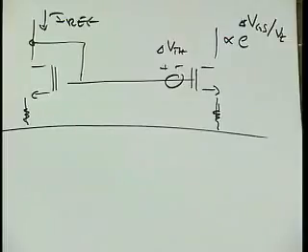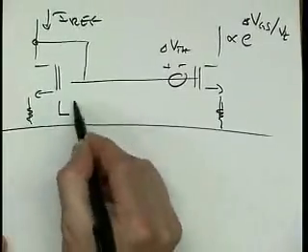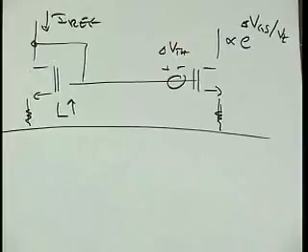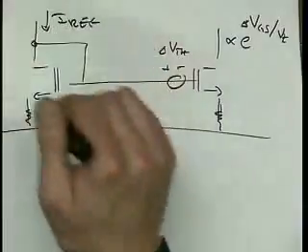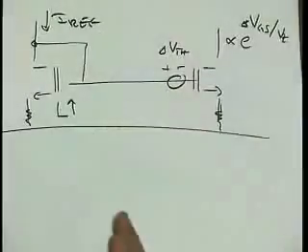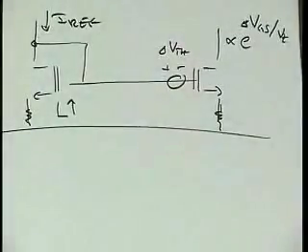What would you do rather? Yeah, specifically, what do you make bigger? Yeah, you make L bigger. That brings the device out of weak inversion and increases VGS, and we don't have the problem anymore. We are not nearly as sensitive. It reduces gm, which is probably okay if this is just for biasing. We don't need speed.